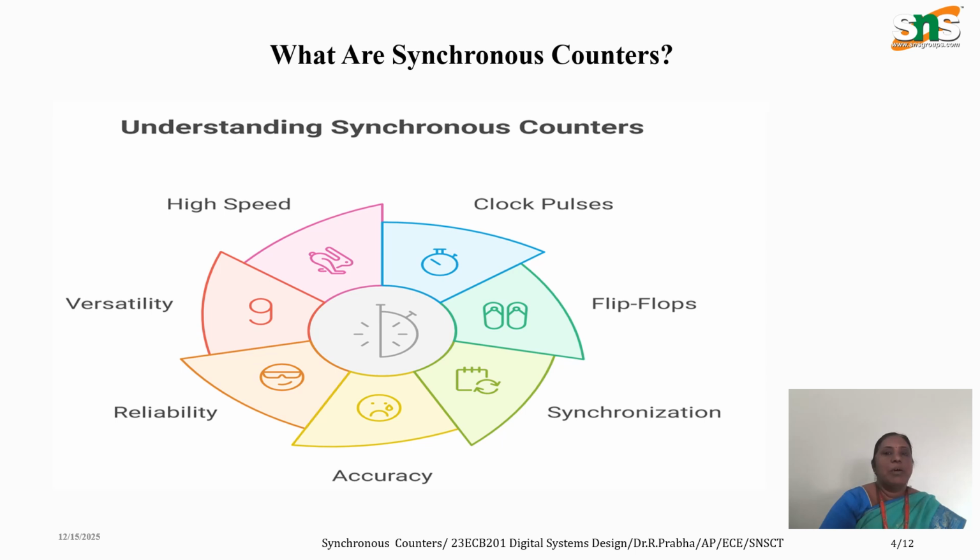The drawback of the previous ripple counter is that it is a low speed operation and not suitable for high frequency applications, and this is overcome with synchronous counters. Synchronous counters use flip-flops synchronously connected with a common clock pulse, and its advantages are reliability, accuracy, versatility, and a very high speed of operation.